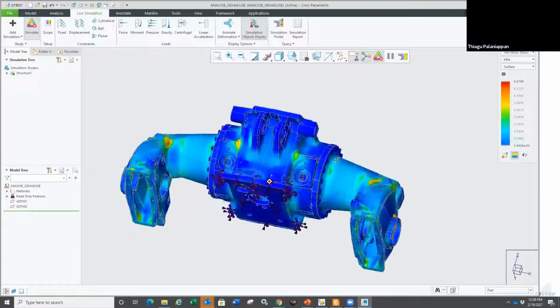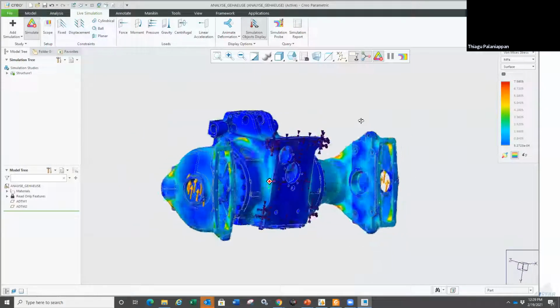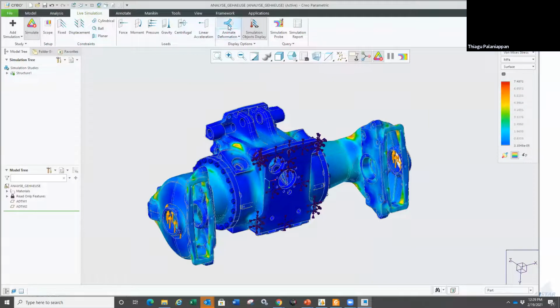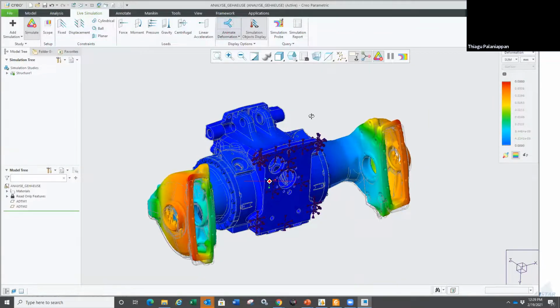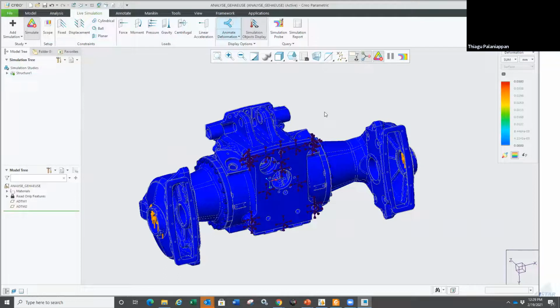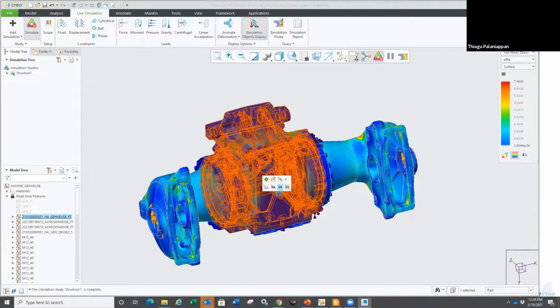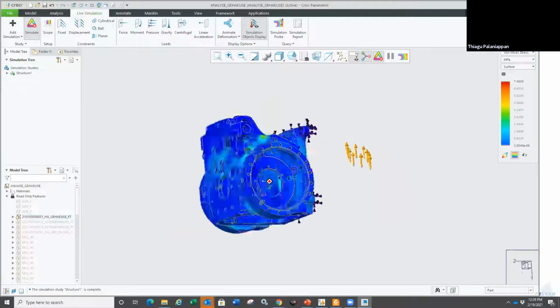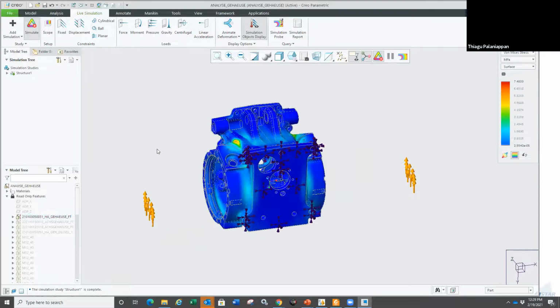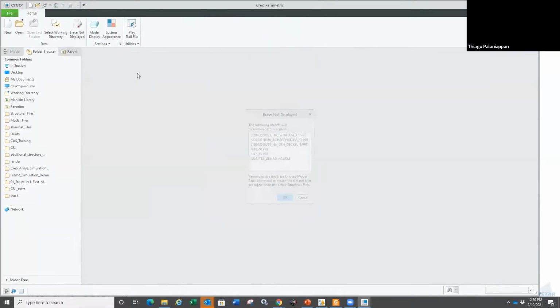And as you can see here, it came out pretty well for a large assembly like that. Quick time. And of course, I can again switch to deformations or stresses. I can do the same probes at specific areas of interest, or maybe I might say, okay, I want to isolate that guy and just look at that component alone. You're able to do all that. So again, from an assembly or complexity standpoint, they're all bonded, and you just want to have some overall direction as to whether you are going the right direction with the design, what my stresses and deflection are. It's kind of useful in that way, right? So that's just to give you